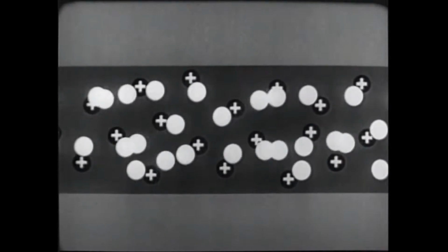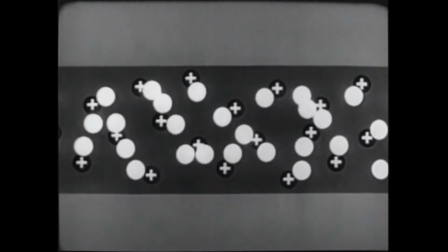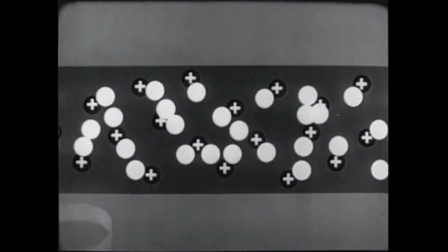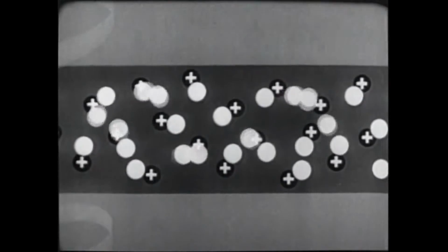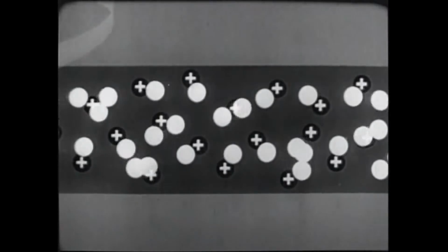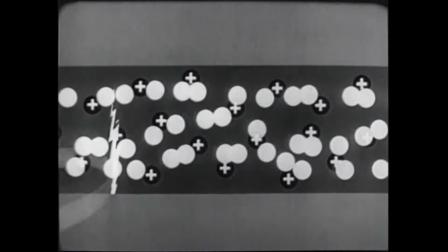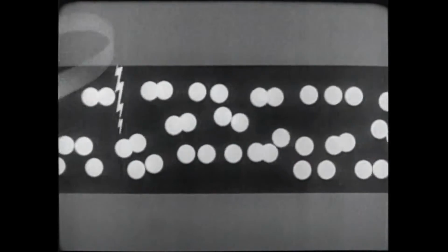In a substance such as a length of wire, electrons are normally moving in all directions. But when a magnetic field is passed through the wire, several electrons are forced from their atoms and move in one direction. Now, in studying electricity, we're mainly interested in the movement of free electrons. So, for convenience, we'll look only at the action of electrons in the wire. When the magnetic field sweeps down across the wire, electrons move in one direction. When the magnetic field sweeps up across the wire, the electrons move in the opposite direction.